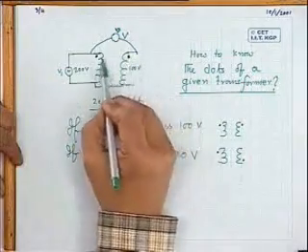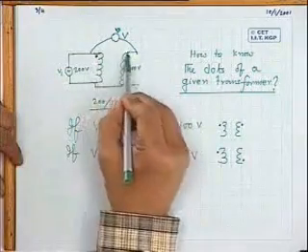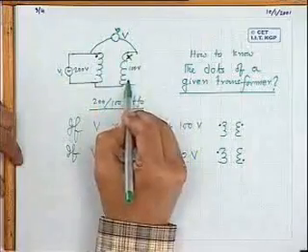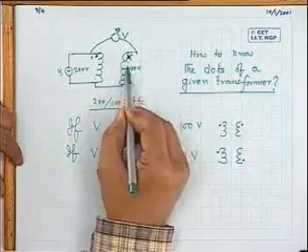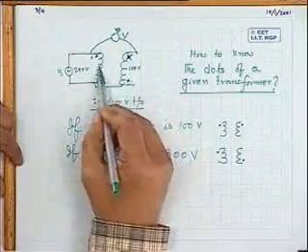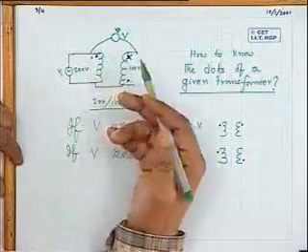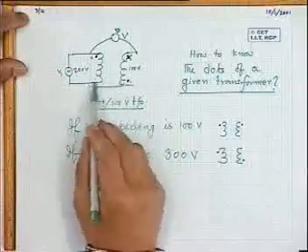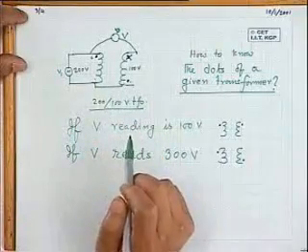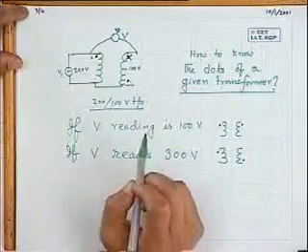You have assumed this to be dot, this is dot. That is, in that case, this will be plus, I mean, you cross it out, this is suppose dot. So you can easily see you start from this one minus to plus, then once again minus to plus, as if two batteries are connected in series with minus plus minus plus. So you will be getting twice this voltage. So that is one way of knowing the polarities by doing a simple test like this.